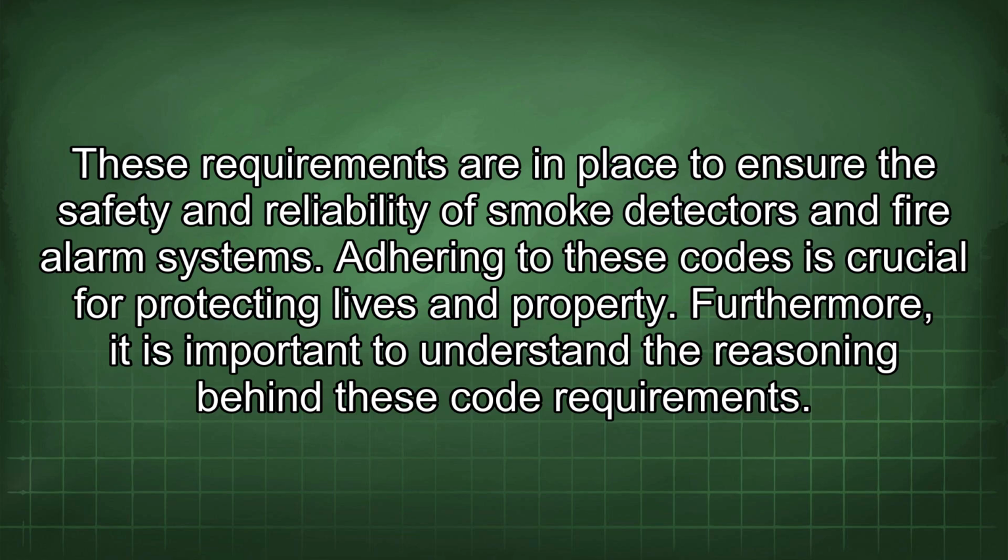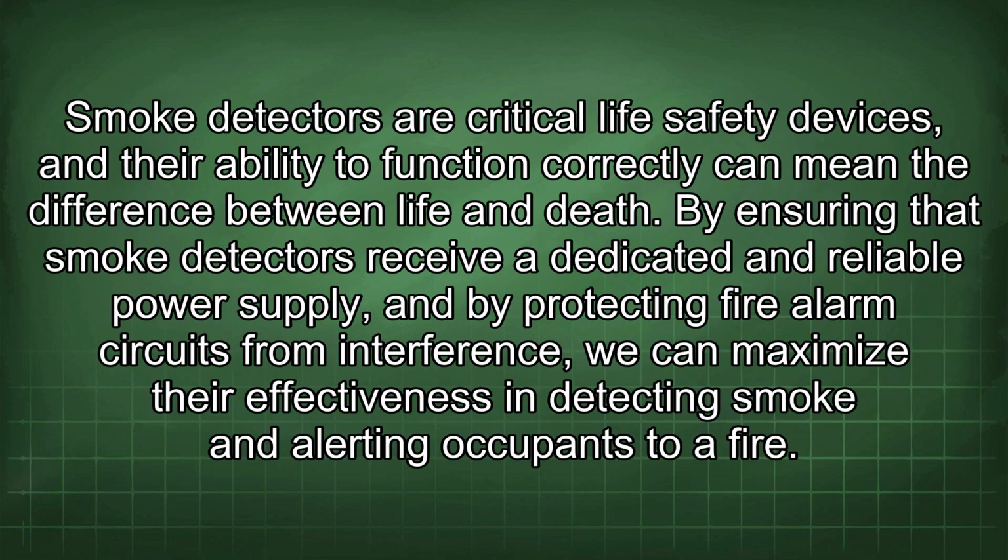Furthermore, it is important to understand the reasoning behind these code requirements. Smoke detectors are critical life safety devices, and their ability to function correctly can mean the difference between life and death. By ensuring that smoke detectors receive a dedicated and reliable power supply, and by protecting fire alarm circuits from interference, we can maximize their effectiveness in detecting smoke and alerting occupants to a fire.